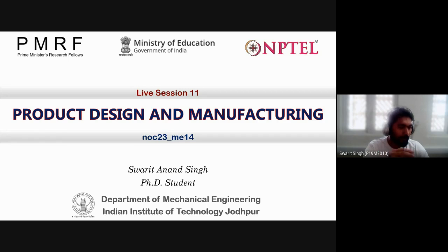For a product, if the operation is performed through hand drilling, then one hand drilling machine, then one manual milling machine, and for finishing, if a manual grinder is required, then one manual grinder. All these three are placed together, so they form the small cell. So it becomes a cellular manufacturing kind of thing.